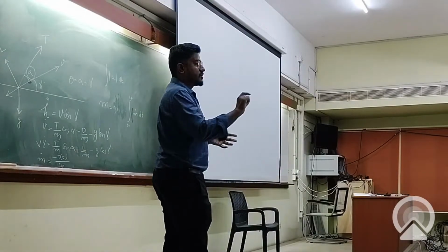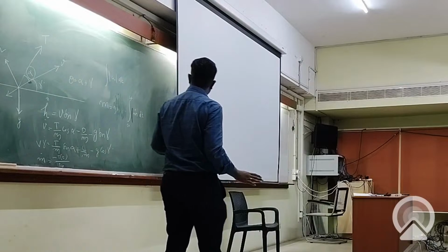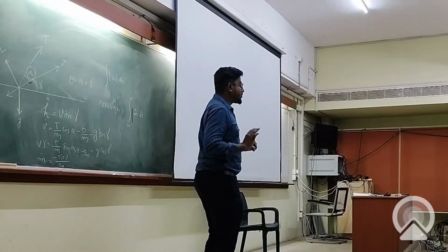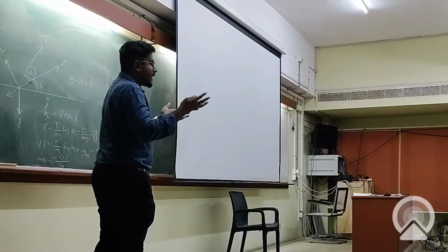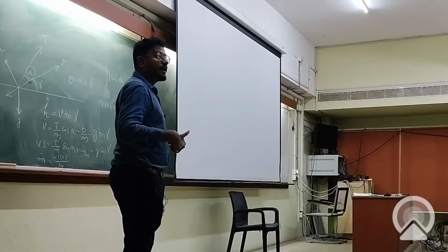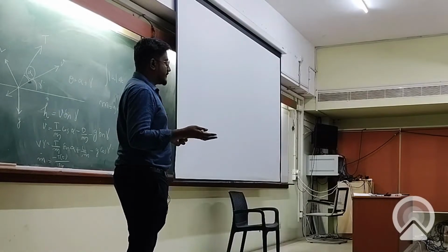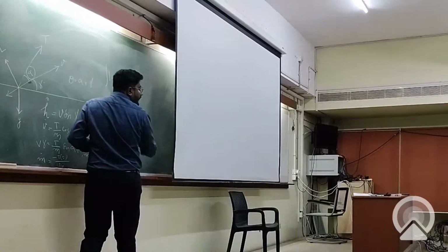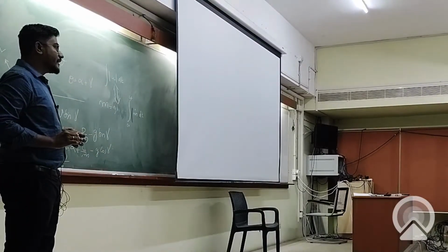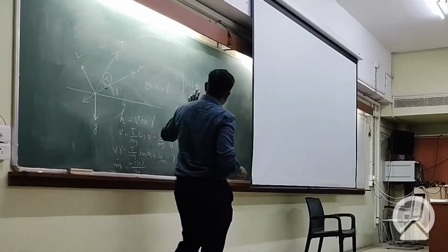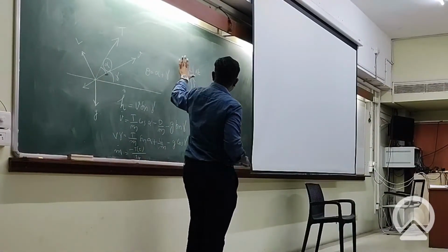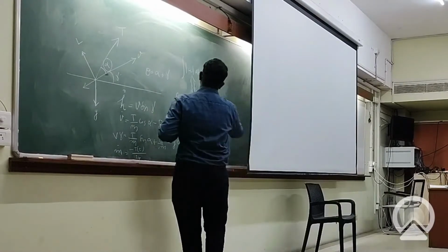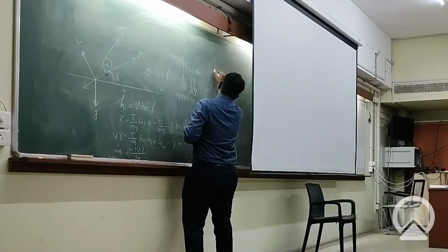What are the losses? The major share of the loss is gravity loss, and steering loss. So when we are trying to optimize the mass in the orbit, we are trying to minimize the losses. Ultimately, minimizing the mass expenditure is the same as minimizing the integral of acceleration.